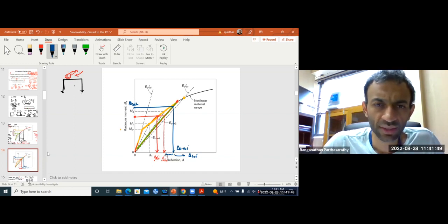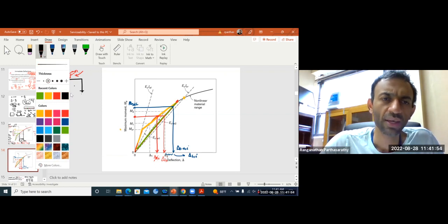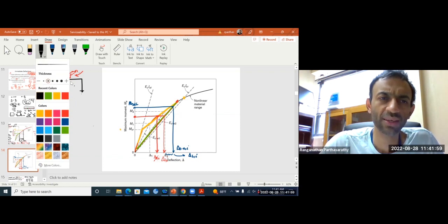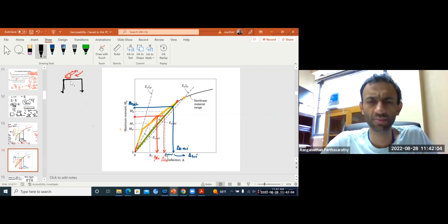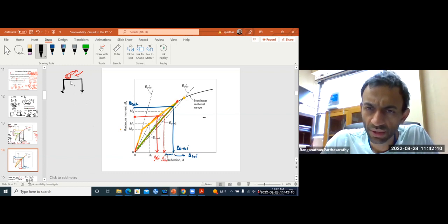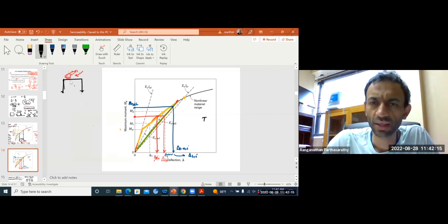As you might have noticed, for any structure it is not possible to exactly know the loading history, that is, what load it saw at every point of time. So there is quite a bit of tolerance which is acceptable in the calculation of deflection. You're okay within about a quarter to half inch, or even a bit beyond that.